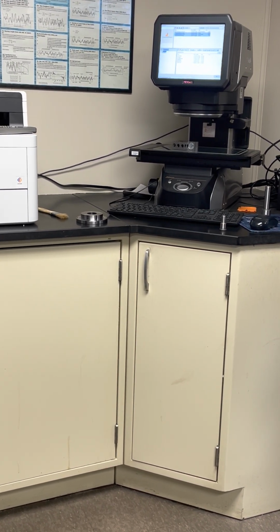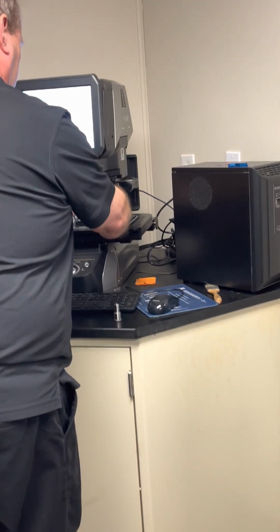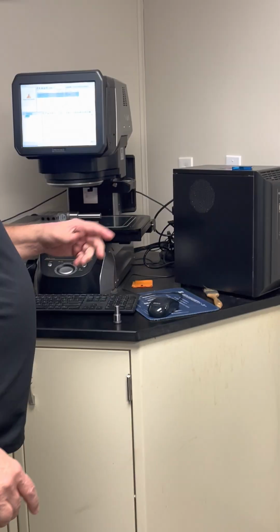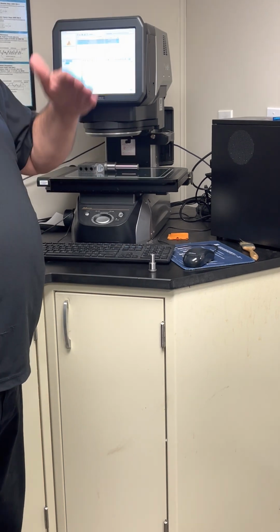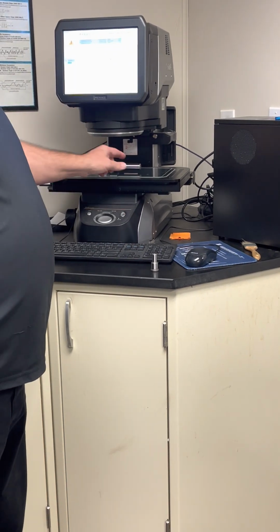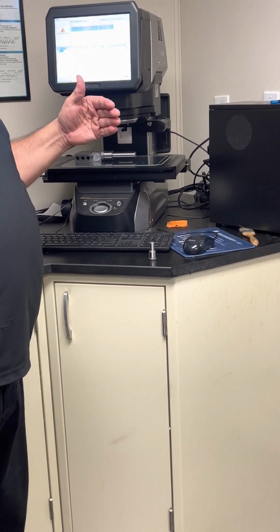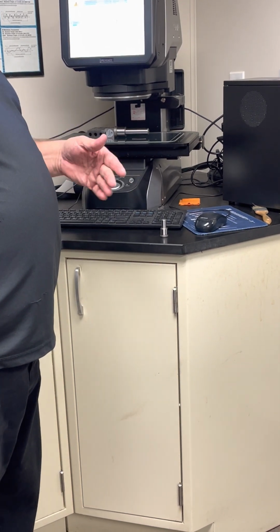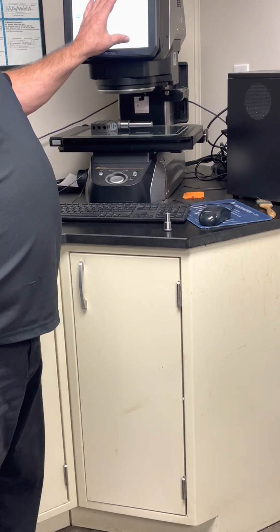So what you could do is basically I could come in here, put this part on. Focus it on this edge, just focus it in on the one edge, and then put one line. Okay, just put a line on there. That's going to lock in your level, your layer. Then I'm going to focus it in up here. That's going to lock in that layer because we only use the two focuses. Now I just simply save the program.